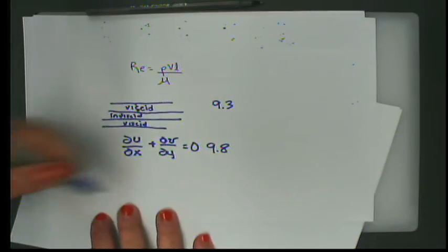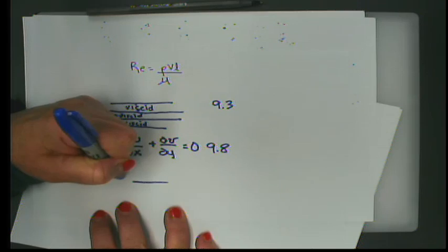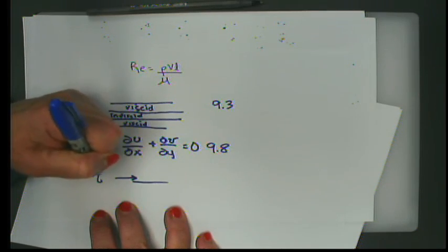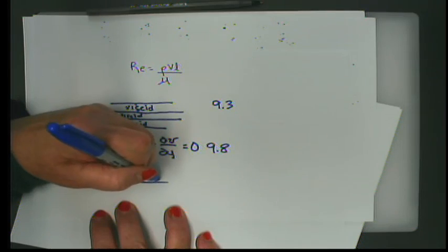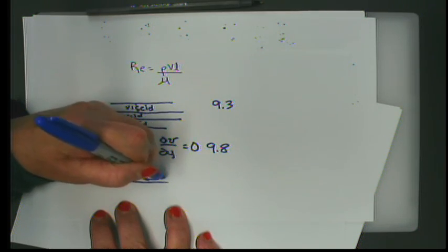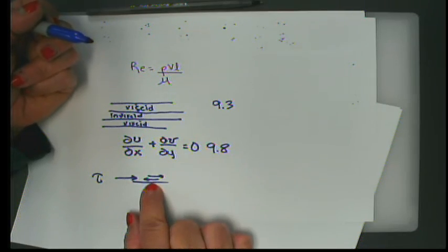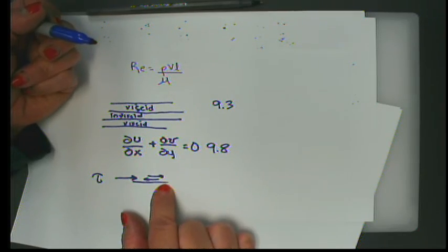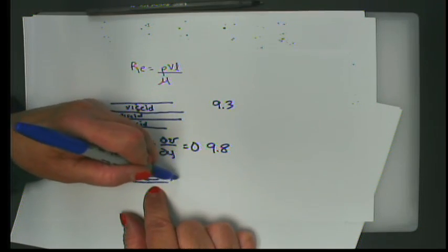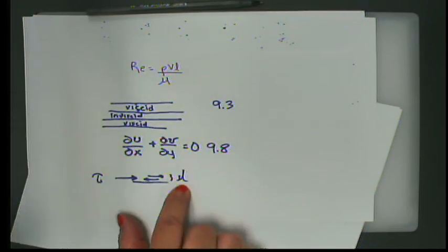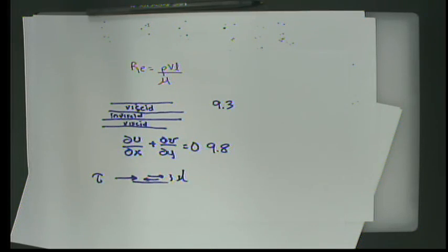And we come up with an expression in shearing stress, which makes sense if you think about the orientation of a shearing stress, considering a tau. If you have a shearing stress tau, that is always a function of forces parallel acting on a surface, and we know that that's not a bad representation of viscosity. So that sort of all makes sense.